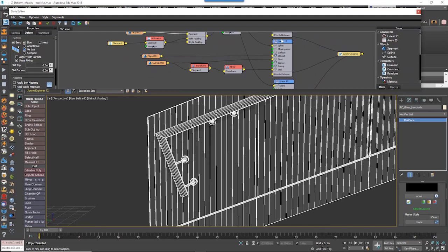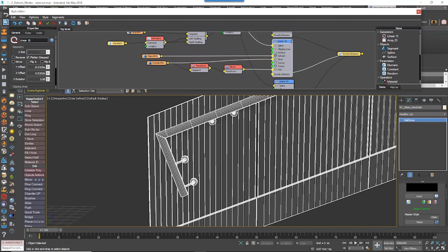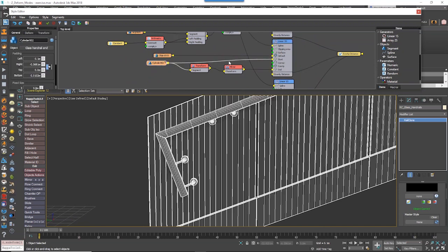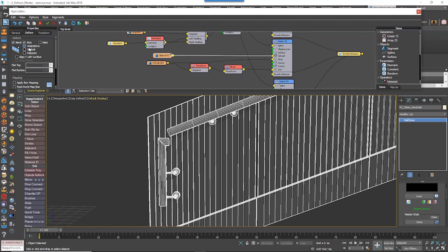And then what about the handles? Well, we can look at that too. These are the handles here. So this is the default input. This is the start input. So let's change this to vertical. And let's change the default, which is the handrail itself, to vertical 2. But, you know, it's not matching up. But I can make it match up by changing the mode. So it lines up something like this.